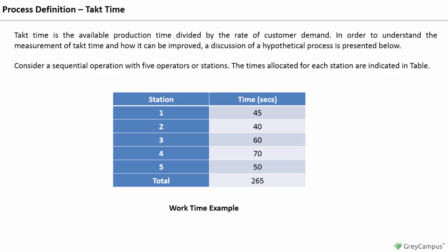Another perspective indicates that 4 operators will require 66.25 seconds. This is slightly more than the desired takt time of 60 seconds. However, the initial task will be to re-examine the content of the operations by looking at the value-added and non-value-added elements. A thorough study may reveal that a significant portion of time can be eliminated, leading to a reduction of 1 operator and possibly a reduction in floor space.